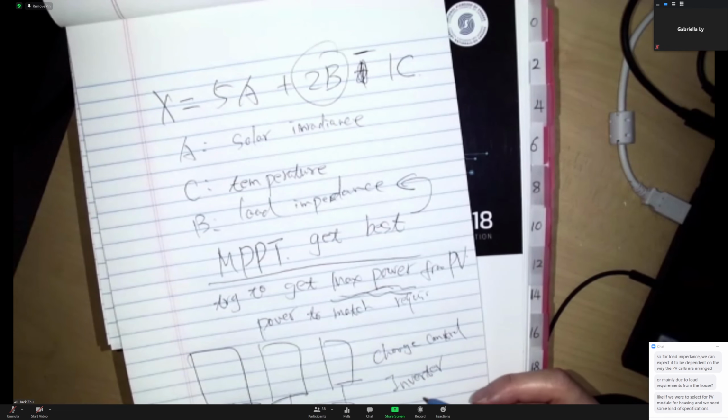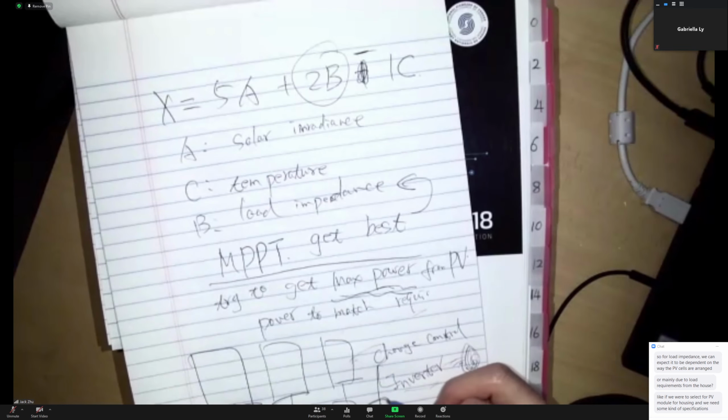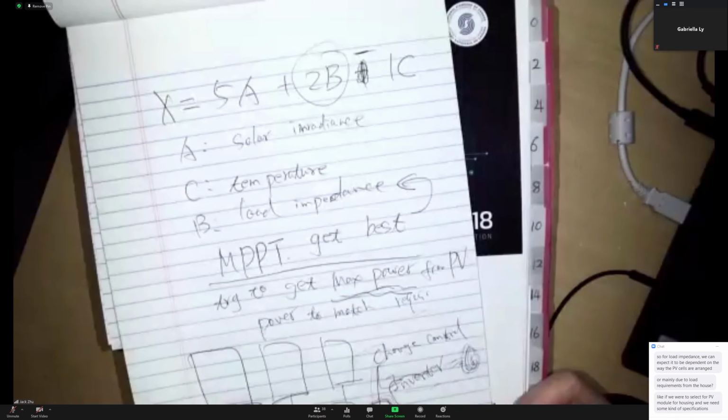But then, because of how much power you're using down there, you're going to change your inverter output. If you don't have a battery, then the demand here is going to change the load impedance. That's why we usually put in a battery down there, so you can always charge the battery and run from the battery to your inverter. This will be a pretty steady load, but also the battery may be over-discharged or fully charged. You're also going to change this.